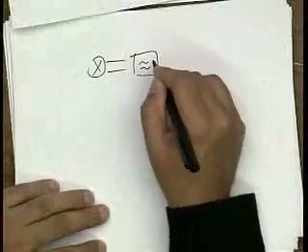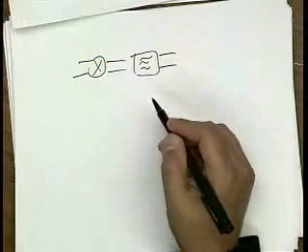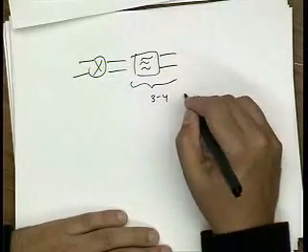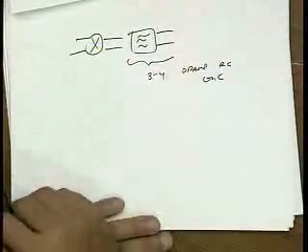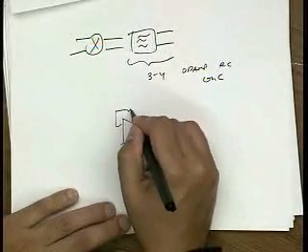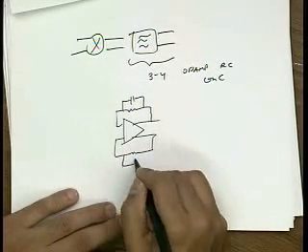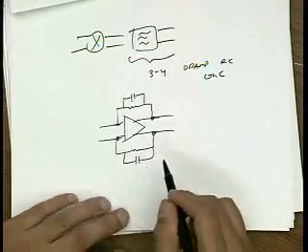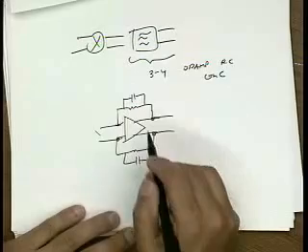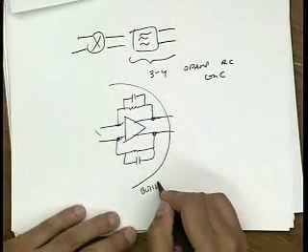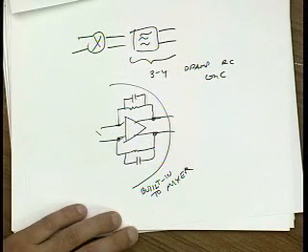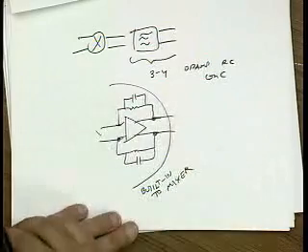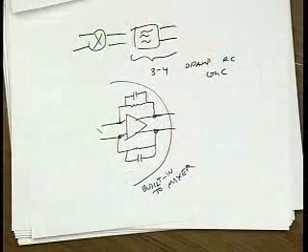So usually the mixer is going to drive a filter. And typically this filter might be, let's say, 3 or 4 either op-amp RC filters or GmC filters. And so it's basically going to be a multi-stage filter. And already you can see that if I put a cap across this op-amp, so instead of putting just R, if I put a C here as well, then I have a low-pass filter. And so this acts like my first filter stage. So this is basically built into the mixer. So I can design the pole frequency here to try to knock out the adjacent channels that I'm down converting in a low IF system.